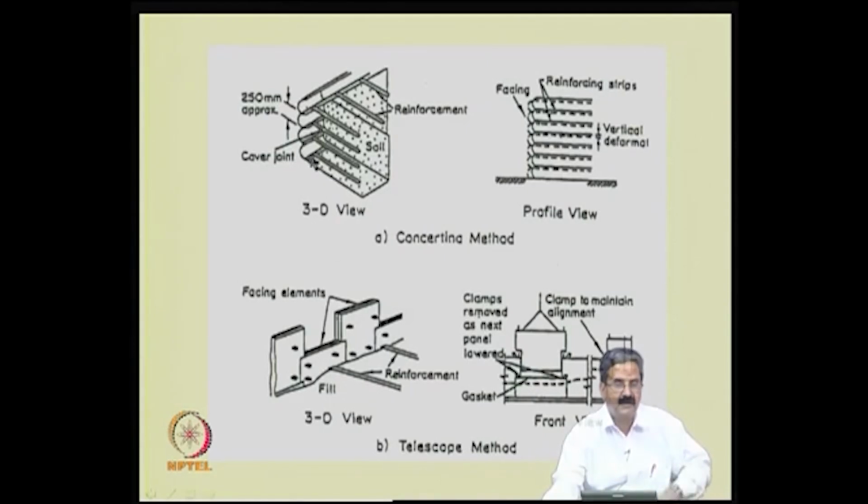In the earlier case, the facing is a simple geotextile material, so you do not have any such problem. You can put simple layers of geotextiles, keep on putting them to some height, and if the tensile forces are taken care of by the geotextile tensile strength, it is all right. The length should also be, as I said, if 10 meters is the height, then 0.7 times that should be the length of the reinforcement. If you satisfy that condition and see that the material stands, you can make an 80° or 90° geotextile slope like this. Keep on doing it: take soil, put the material, take soil, put that geotextile, and compact it. Of course, you have to compact all that.